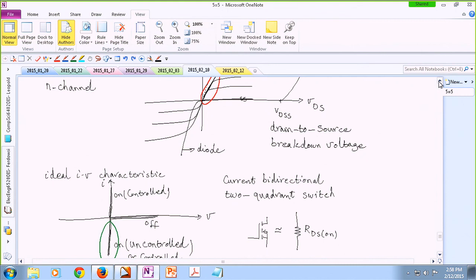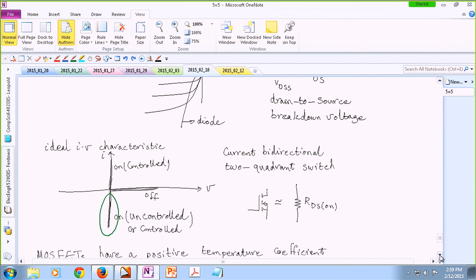So it's not something that you really have to worry about. So it shouldn't damage the MOSFET with a reverse voltage spike? Yes, that's right, it doesn't damage it. The diode is taking care of that, basically. Although you can argue that if you damage the diode, you have killed the whole thing, because the diode and the MOSFET are not separated from each other anyway. But I wouldn't worry about it. It doesn't really kill anything.